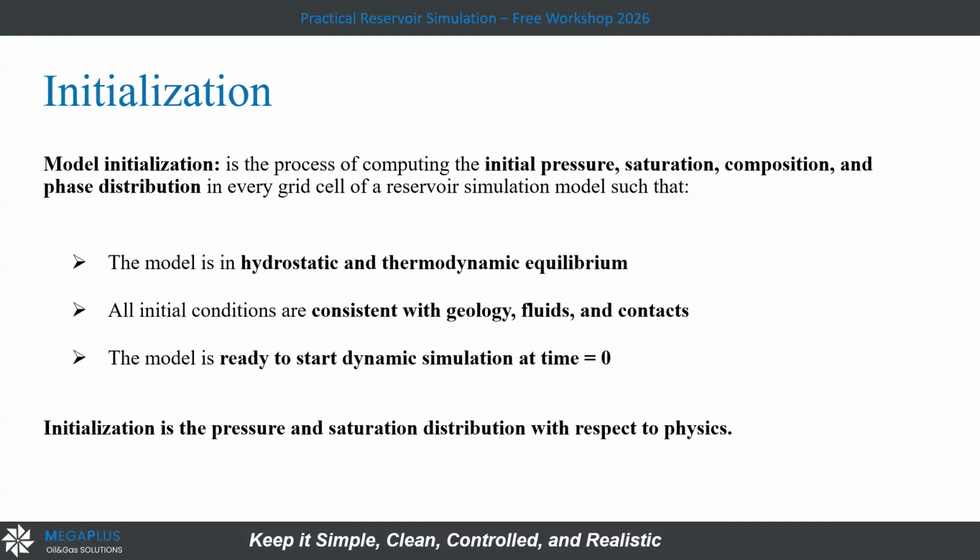So we will start the first step, initialization. And as I told you, if you have a project, a full field simulation model, it could take 6 months or more, and the milestone of the project will be the initialization. In initialization, you put in all the inputs you inserted, the pressures, saturations, and all of this, and then calculate the dynamic volume, respecting the property model and the structure model.